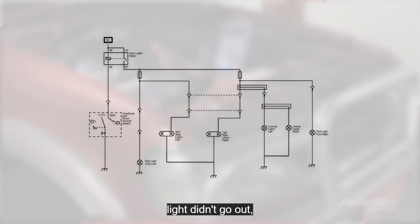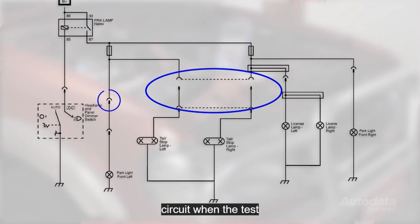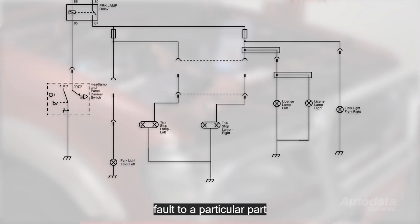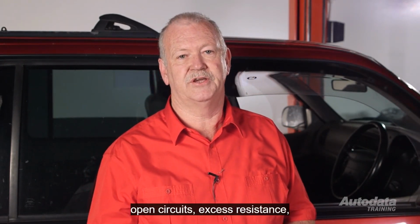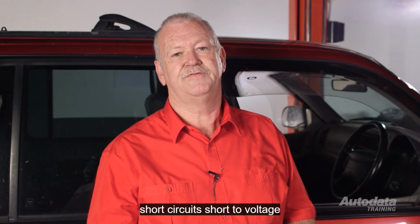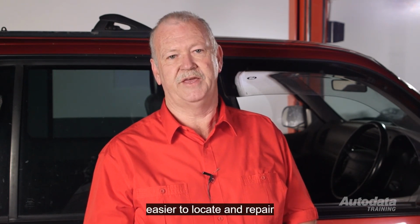If the light didn't go out, you would then move to the next connector along the circuit. When the test light goes out, you will have isolated the fault to a particular part of the wiring harness. That's the procedure for locating open circuits, excess resistance, short circuits, short to voltage and short to ground. Using these simple methods will make it a lot easier to locate and repair these faults.